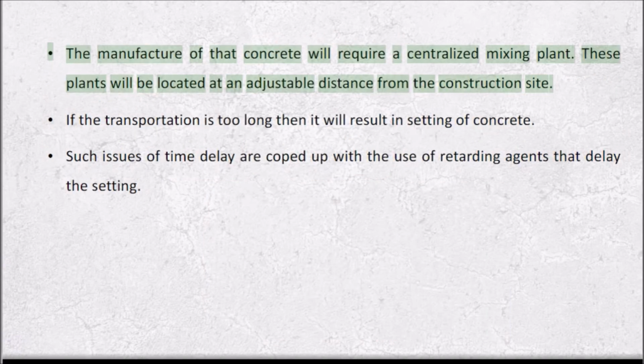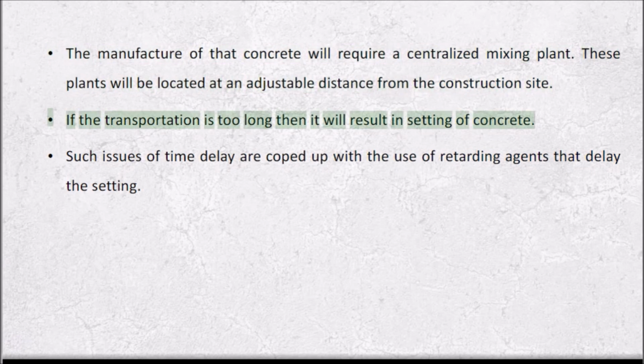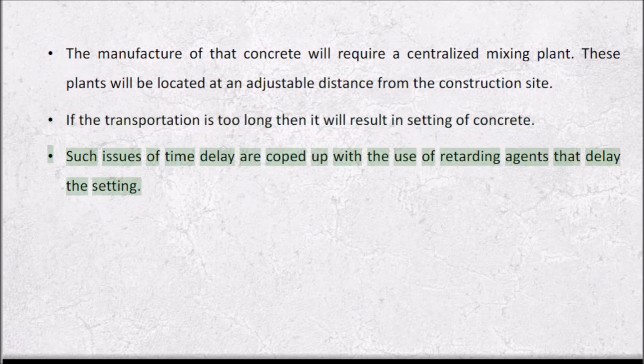The manufacture of this concrete requires a centralized mixing plant. These plants will be located at an adjustable distance from the construction site. If the transportation is too long, it will result in setting of concrete. Such issues of time delay are coped with by the use of retarding agents that delay the setting.